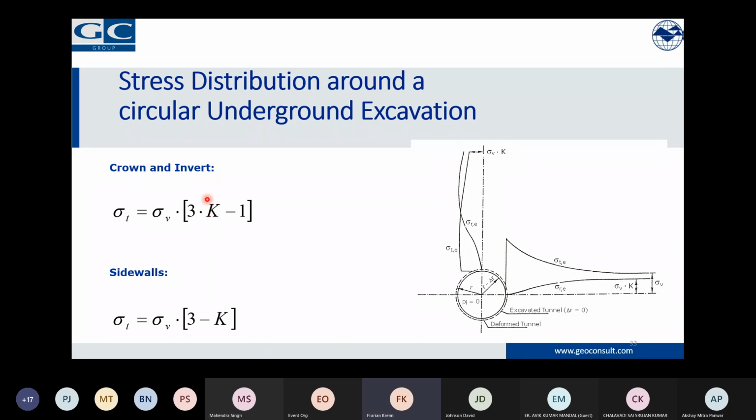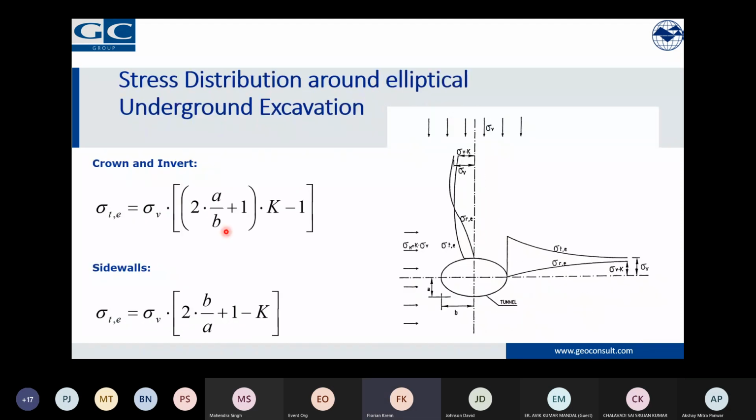And you can see here one factor is coming in, that's the coefficient of side pressure, which in rock tunneling may vary quite substantially. If we have a tectonically active area, then the K0 will go beyond 1. Usually in the first check in a normal rock tunnel, you will come to 0.5 as the usual applied value. Now, intentionally, I put in here also the elliptical opening.